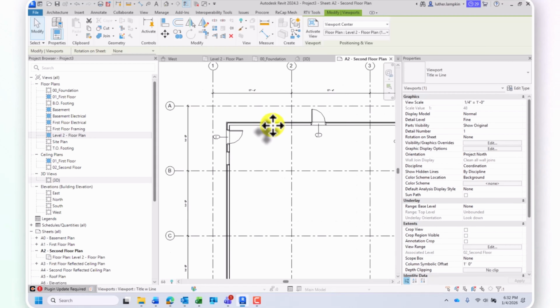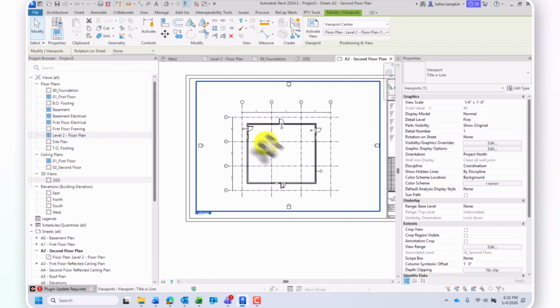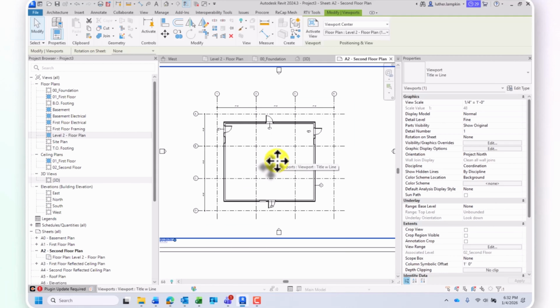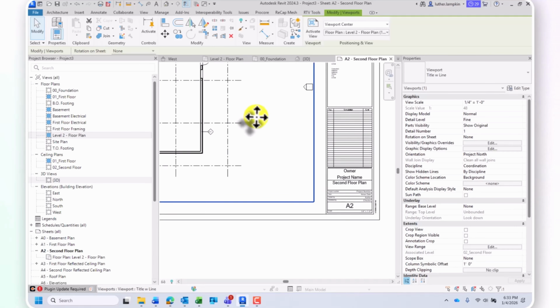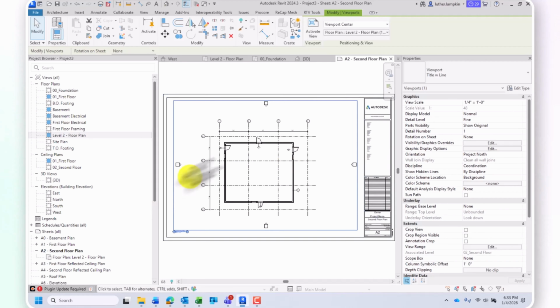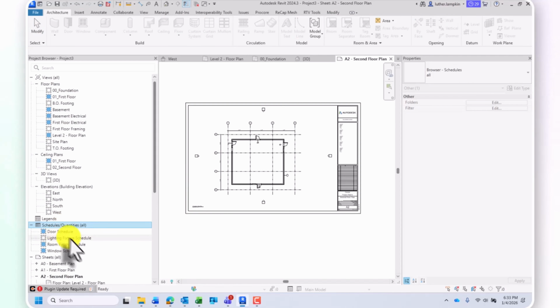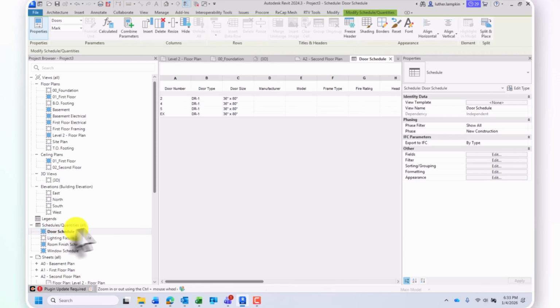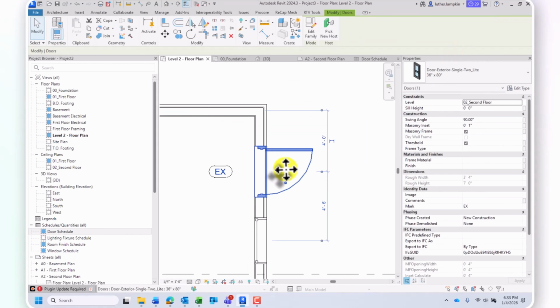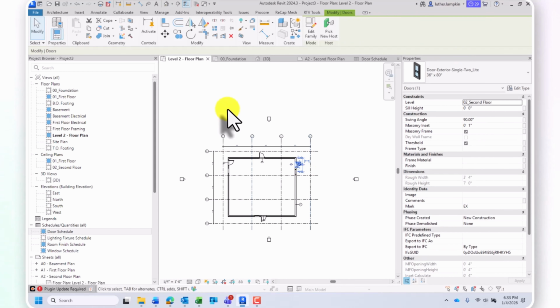Now, what we did before is we showed we can do grids, grid outlines, doors, windows, sheets, as you can see right here. And it's super important. Now, the true power of Revit is not just generating the sheets. If I go over to schedules, like the different door schedules, with all the information that we've been filling out, I click on the door schedules and look at all these different doors. If I go to any one of these, see all the ones we just created? Watch this. If I go to highlighted model, true parametric. Look at that. That is how we want to leverage Revit.